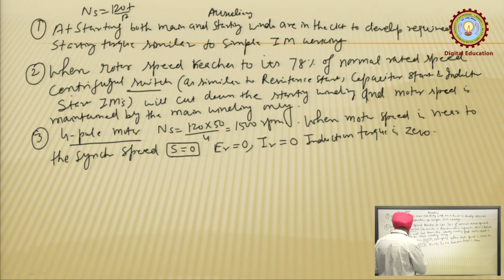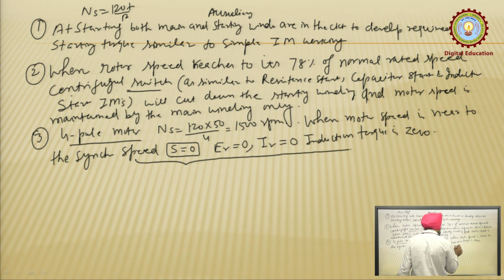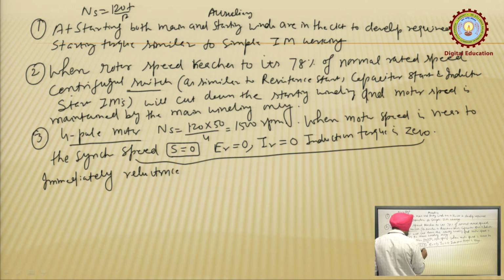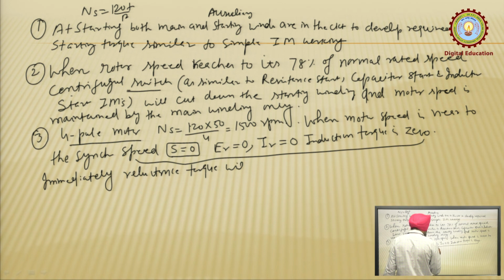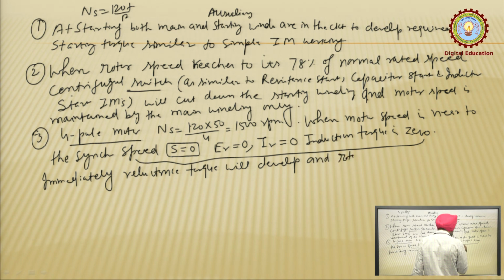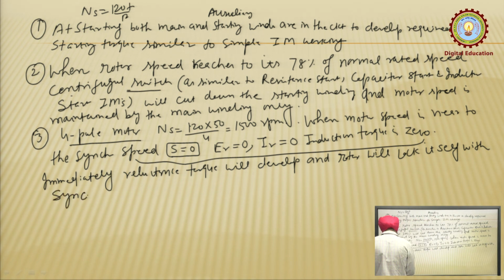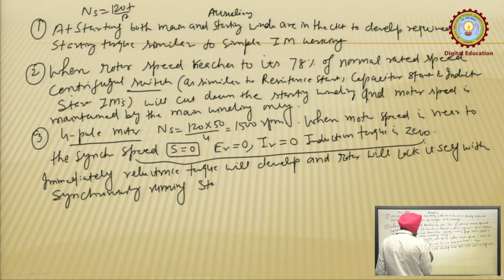Okay. See, when this condition is attained, that induction torque is 0, immediately reluctance torque will develop and the rotor will lock itself with the synchronously running stator's flux.